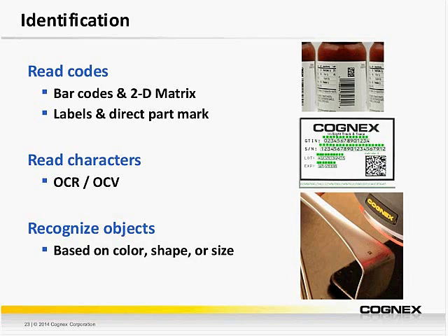Direct part mark, or DPM, applications have the code or character string marked directly on the part. It's commonly used in the automotive, semiconductor, and electronics industries for implementing error-proofing methods, enabling efficient containment strategies, monitoring process control and quality control metrics, and quantifying problematic areas in a plant such as bottlenecks.